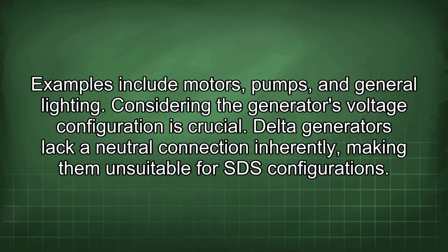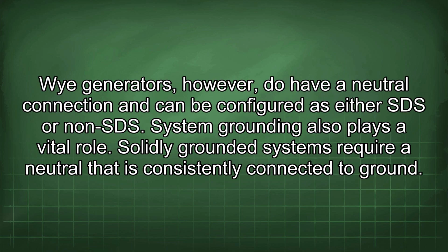Considering the generator's voltage configuration is crucial. Delta generators lack a neutral connection inherently, making them unsuitable for SDS configurations. Y generators, however, do have a neutral connection and can be configured as either SDS or non-SDS.